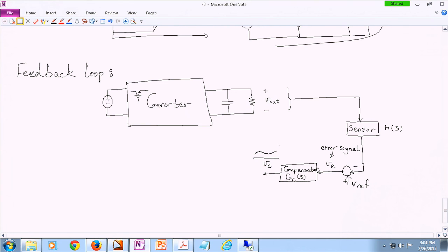So it's this level of the signal, you have to convert it to a duty cycle, like a pulsating signal. So you got to use a block here. It's called pulse width modulation. So you get this pulsating signal of zeros and ones.